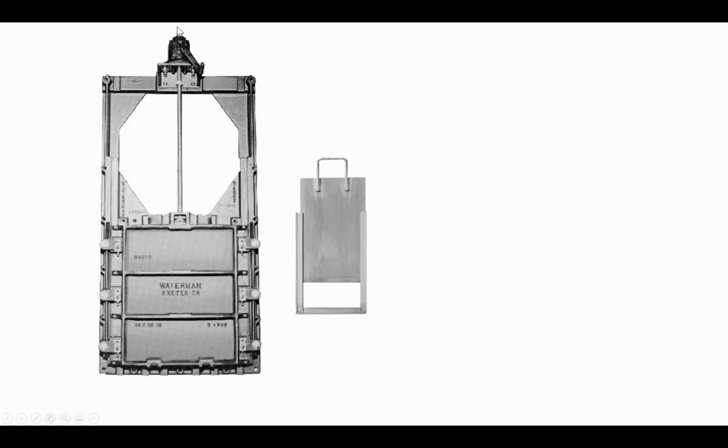And someone who's trying to regulate the flow would simply open up the gate using the handle, open it up a certain amount, and then that would dictate how much water is flowing out under the gate, maybe into an irrigation ditch that's going to be used for watering a crop. The problem is that this metal plate may be fairly heavy, and so when you get beyond a certain size, it may be necessary to put in a crank, and it may have gears, and the length of the crank maybe would give you some leverage to help lift the gate, or it may be that they put an electric motor on the top.